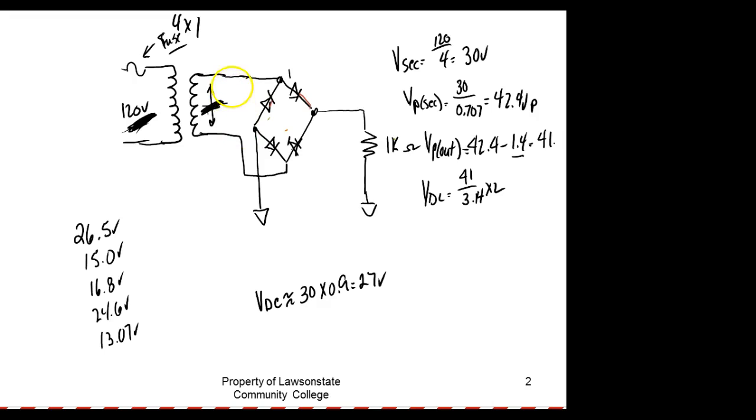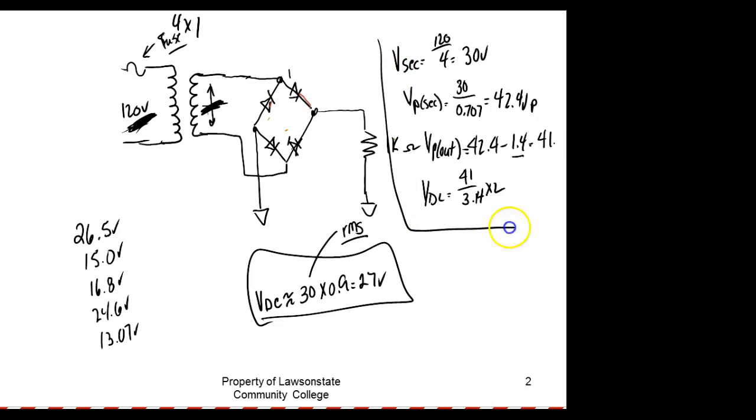It's the secondary voltage that sets the output voltage. So the first thing we need to do before we can even use this formula right here is we need to know the RMS secondary voltage. But what's nice about this is that in this formula we can use what? We can use RMS. So that saves a ton of math. Look at this. So we did all that to come up and get what? 26. What's that? 26.1 volts. We did this and came up and got 27.